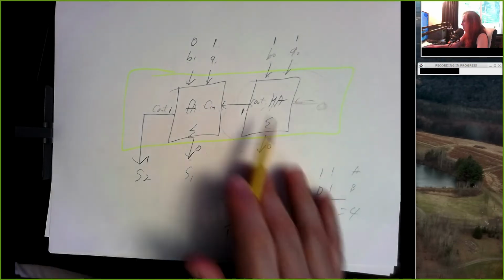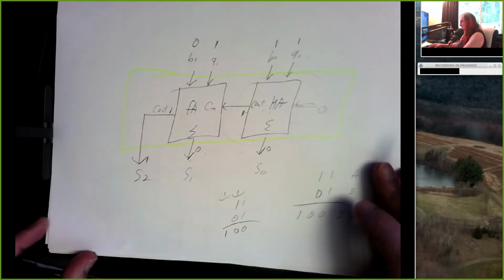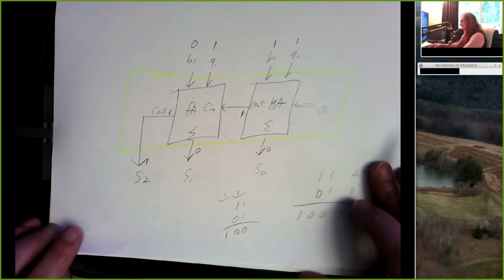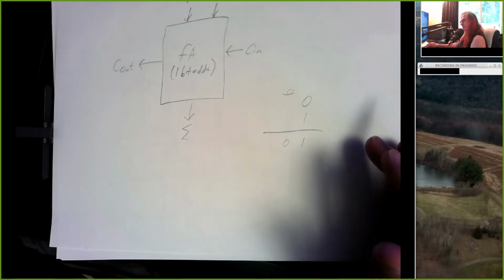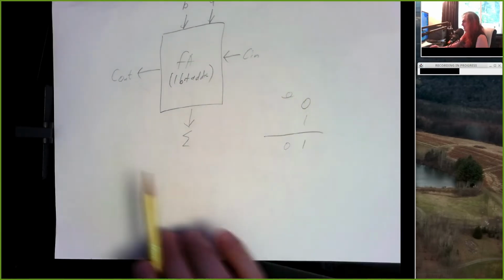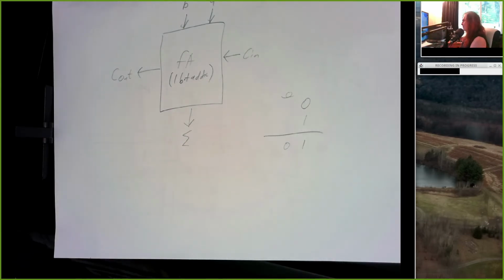Or maybe you can fit them all on one big proto board. But spend a little time thinking about floor planning, how you're going to put these things onto your proto boards. And then, ideally, if you have a hard copy of your schematic, you can get a highlighter and go over the lines of the schematic as you put the wires into Tinkercad.